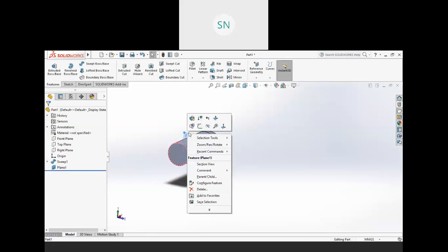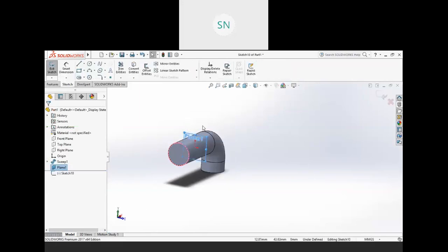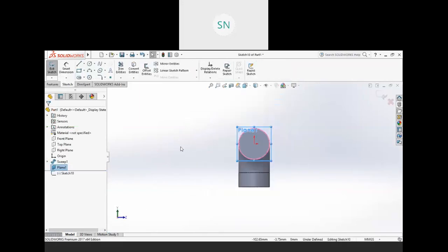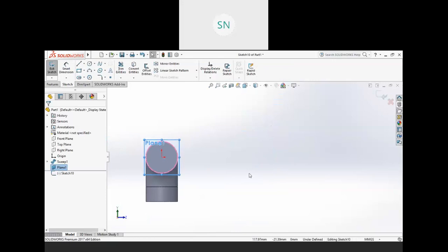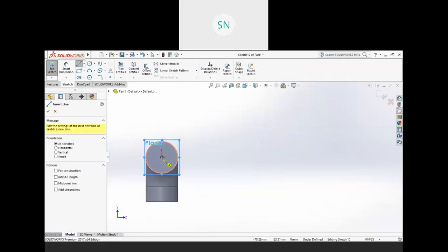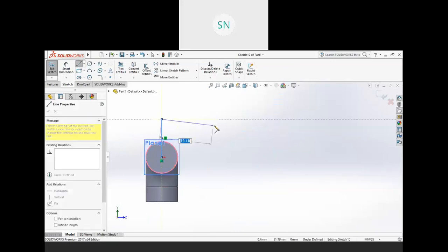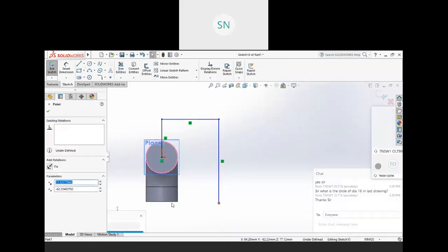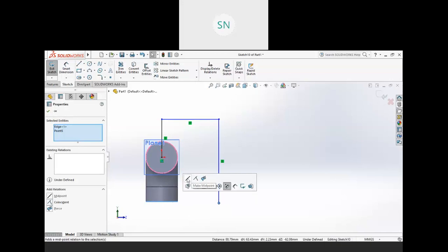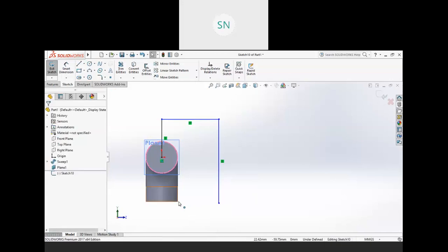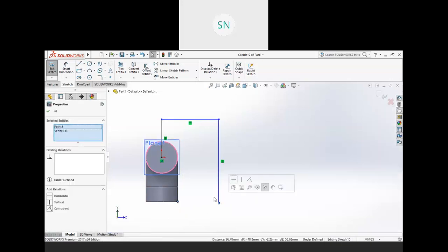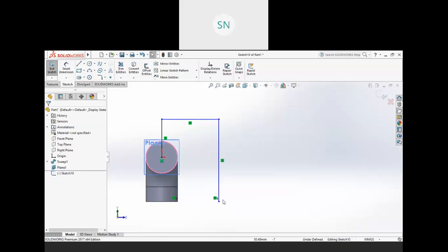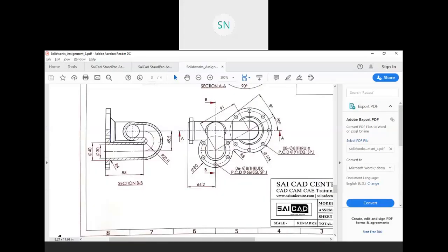And now create a sketch on this plane. We'll begin with a line like this, then here, then again here. And this point with this line should be horizontal. So let me make this point horizontal. Okay, so the bottom base level is given.